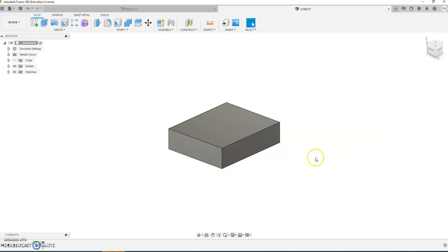If you've done it correctly, your block should look like the same proportions as mine. If, again, as I said the last time, if it looks like it's too thick, come down here and modify or double check your extrusion. Make sure you extruded it properly. If it looks like it's the wrong shape in the other one, come down here and double check your sketch by double clicking on it, and make sure you have it 2.5 by 3. If it looks like this, great. You got it.